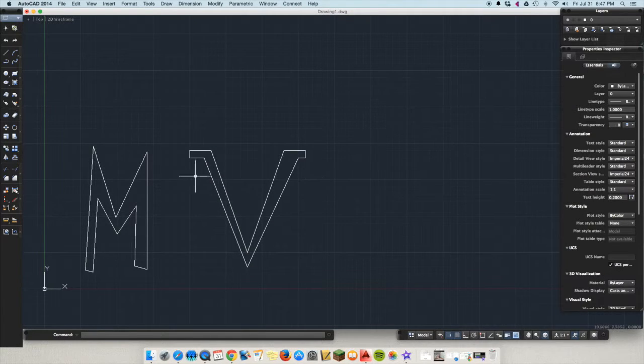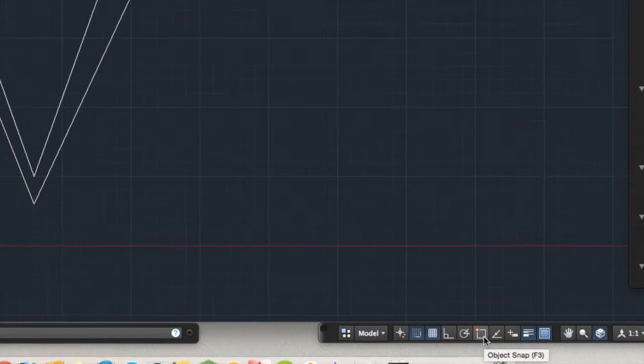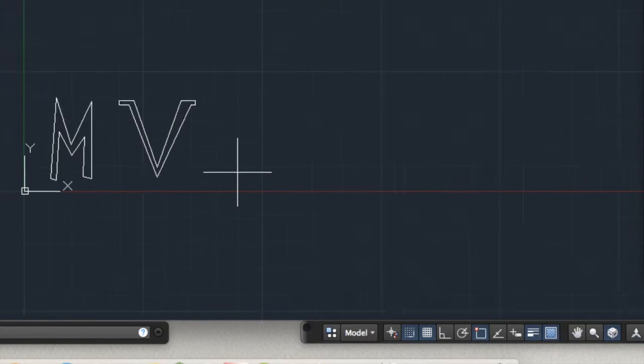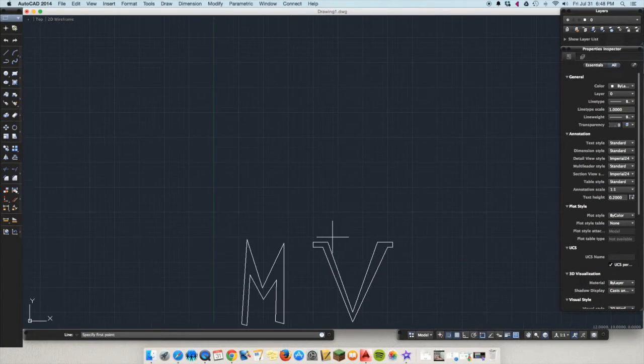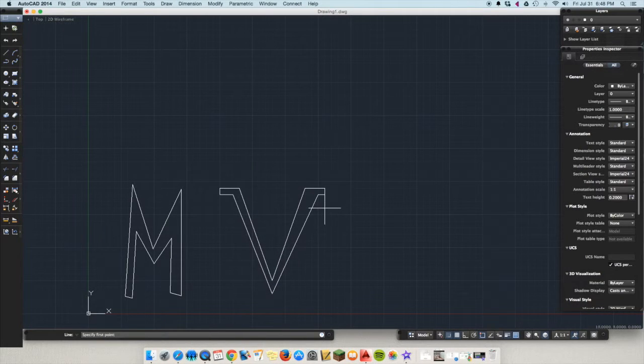So I would draw it first in the program, and then if you need the coordinates back, you can click the line tool like you're going to draw it again and trace over it again. And what you're going to do is down here on the status bar, there's a function called Object Snap, and what Object Snap does is let you hover over a point of an object you've created and start from that object, but we're going to use that to read the coordinates over there. So this is 18 x, 9 y, and you can see that way down in this corner way over here. So that's what I would use to do your V, and you'll give me that on a piece of paper.